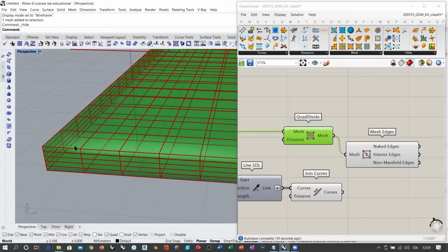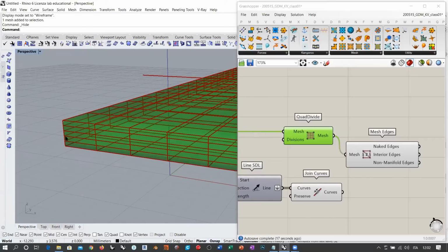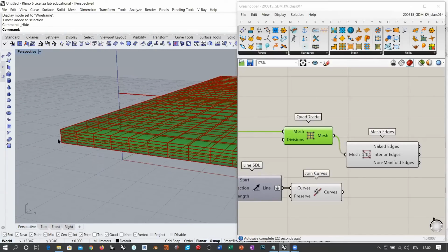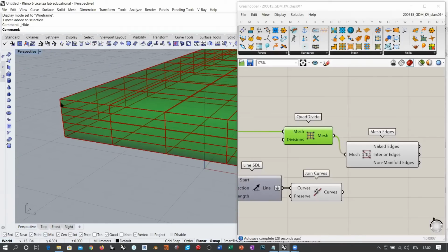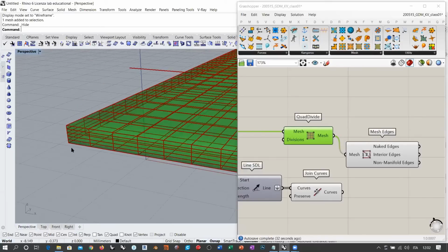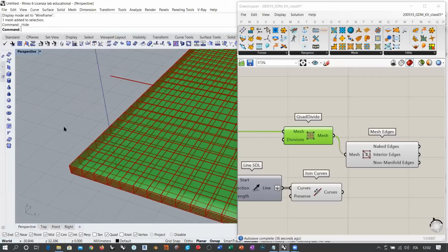We had just one quad, okay? But now this one quad is being split into 5 by 5 polygons. And so we have very small edges vertically along the side of this mesh. This can be a problem because when we program elastic properties for these edges here, either they tend to expand. So if they expand, this part here is going to expand more vertically, okay?